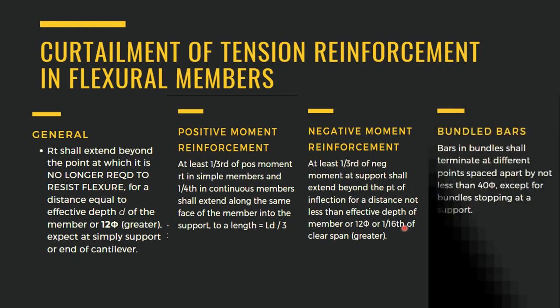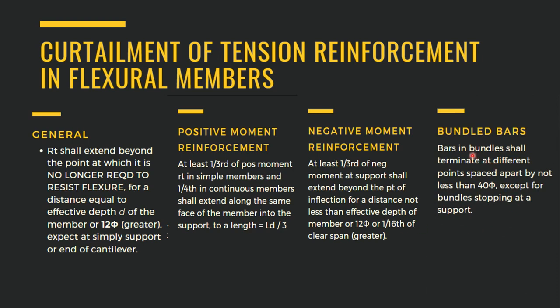Now in case of bundled bars, bars in bundles shall terminate at different points spaced apart by not less than 40 times the diameter of bar, except for bundles stopping at a support. These are some provisions or specifications provided in the IS code.